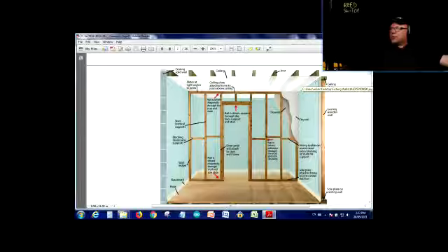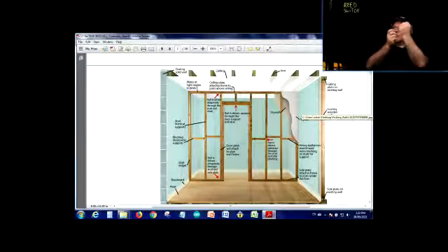It's okay to run wires here, because you have a bit less than 2 inches of free space to run your wires inside the wall. Now, quite often, the way to check that, sometimes just a quick check, is to bump it with your hand to see how the wall behaves. Is it hollow inside, or is it just giving you a hard reaction to your tapping?